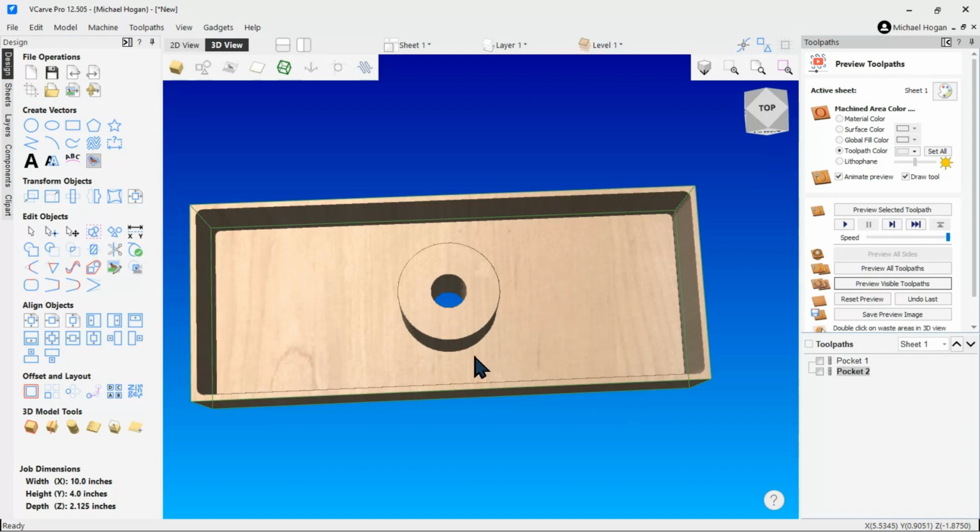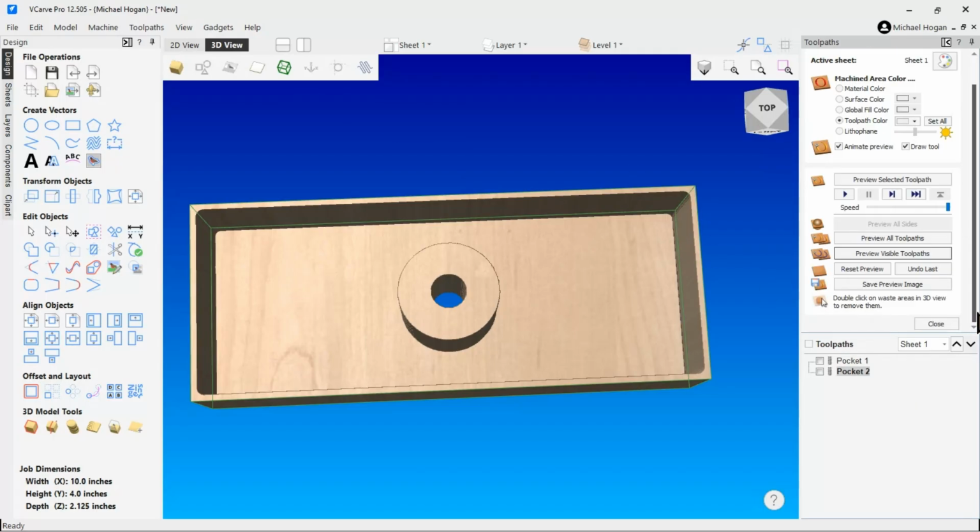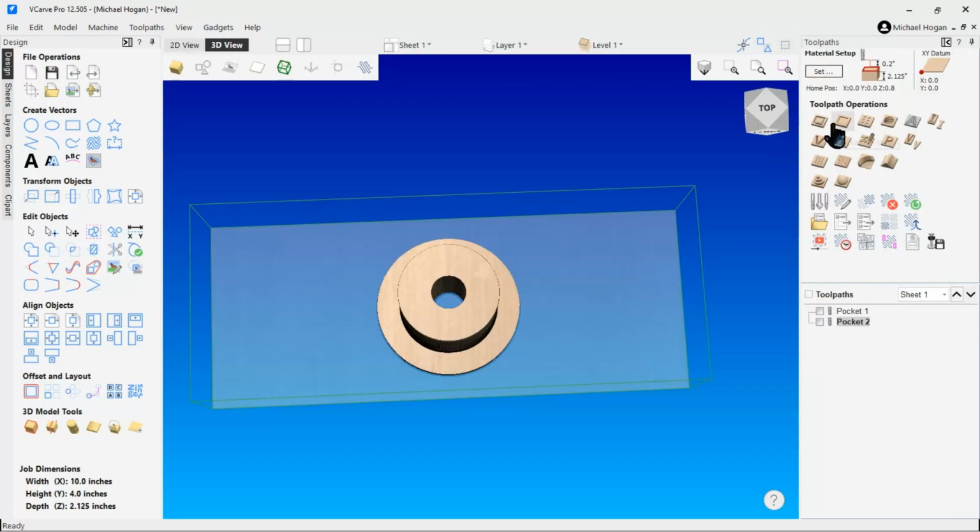Now we're going to cut the model out from the material. So now what I can do is close this. And why I'm doing all this is I want to show you that that 1.875 is going to leave a 0.25 thickness, which is what I gave this bottom piece or bottom segment. So that's what we're trying to create.